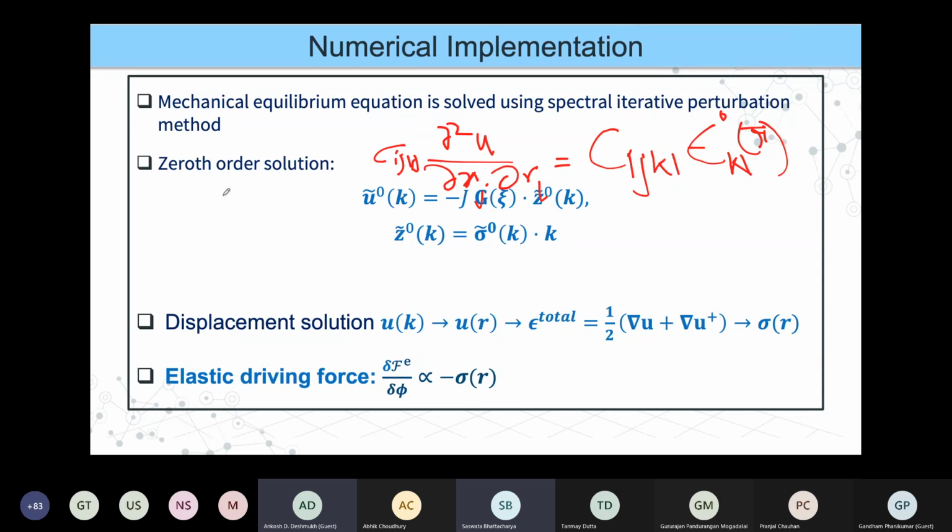In the Green's function method, in general, either you use a delta function or you use Fourier transforms. Since u is periodic, we can directly use the Fourier transform, and if we use that, then we find the term C_ijkl n_j n_l, which is basically my G_ik, that G tensor that you can see. And here j is the complex number, j is root minus 1.